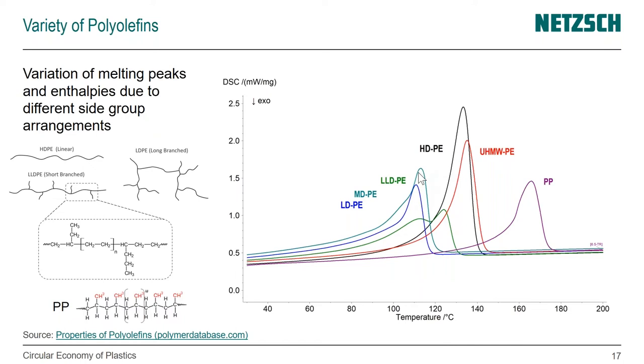We have problems with the overlap of LDPE and LLDPE because we very likely would underestimate the LLDPE. You see, the LLDPE often has this bimodal distribution, with two peaks because of the branches that we're picking up.